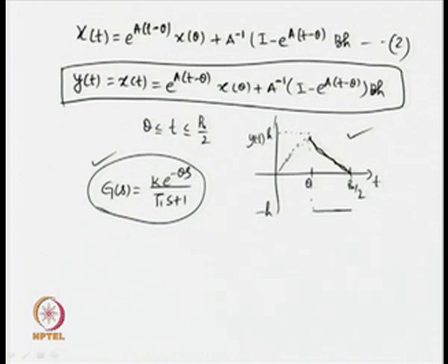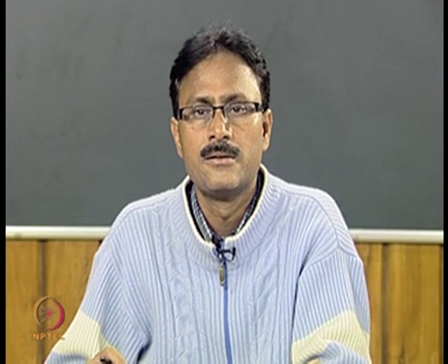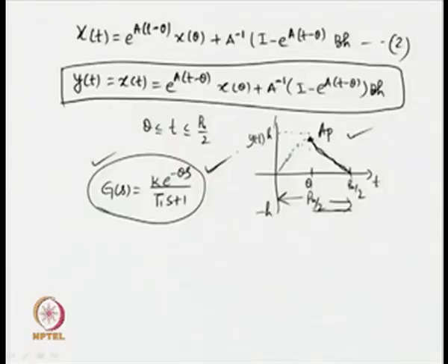So, the measurements made on the output, what measurements can we make? We can measure the peak amplitude of this output. Also, we can measure the half period of the output using zero crossing detectors. When the measurements are made and when the expressions are found to be involving those measured quantities, then it is not difficult to solve the analytical expressions and find the unknowns associated with the transfer function model.